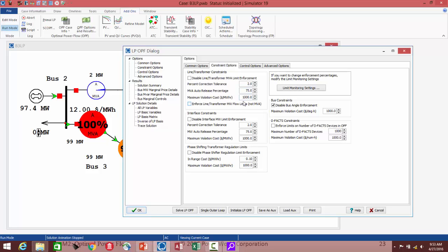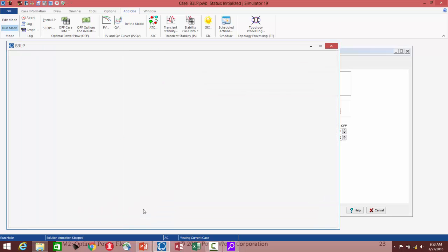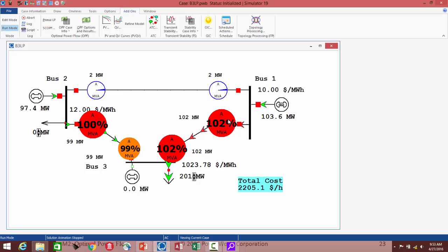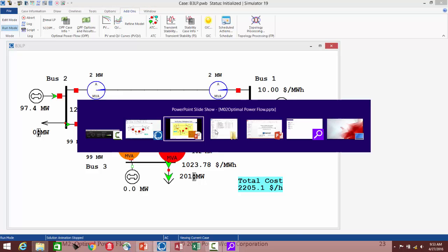It's really just important that it's sufficiently high that the software is going to try to meet the constraints by moving the other controls, by moving generation, or if load is available as a resource, adjusting load, and so on in order to get the costs down. But if there are no controls available, then the limits are violated and it's considered an unenforceable constraint.